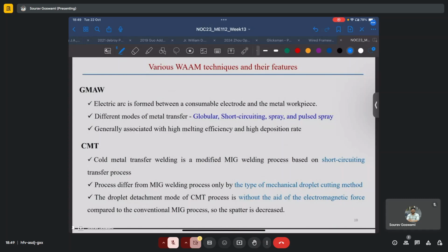As we remember, here the wire is melted and the molten volume of material is lowered into the existing bead or melt pool. And once they make contact and the short circuit is detected, rather than relying on a shooting up of the electric current, which will lead to joule heating and then breaking up of the wire because of the localized heating, we mechanically pull the wire back whenever such a short circuiting is detected. This prevents the spikes in temperature and also lowers the amount of spatter.